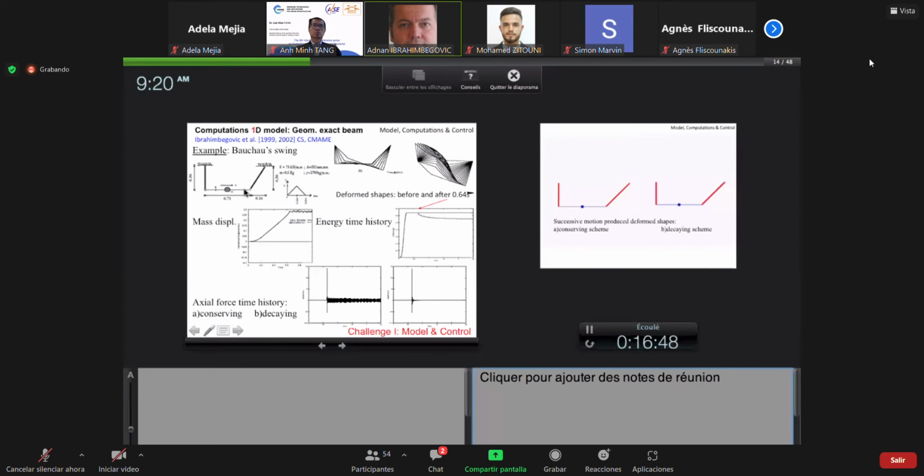And this has all been modeled by beams, and you know beams, being very slender, have a much bigger stiffness with respect to the axial deformation as opposed to the bending deformation. So the initial phase of the swinging is dominated by the bending deformation. In other words, you have a very low frequency. And then once you start turning the direction of this other part, you introduce high frequency because of the axial deformation. So you can see at that moment that energy conservation really starts having a decay,